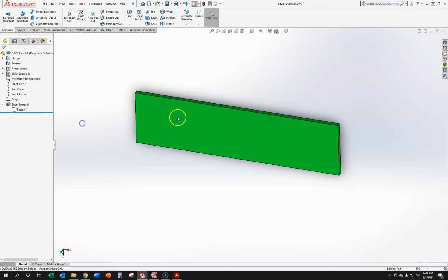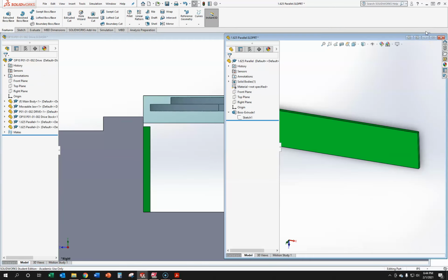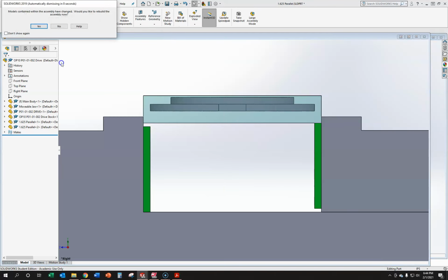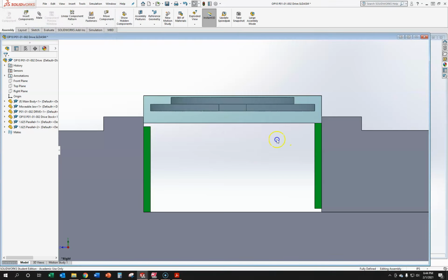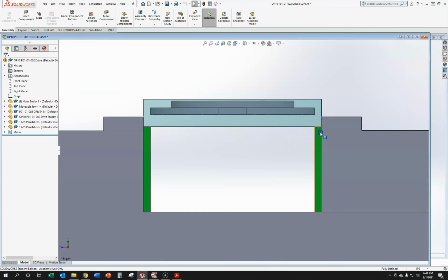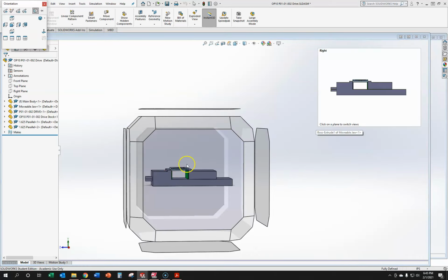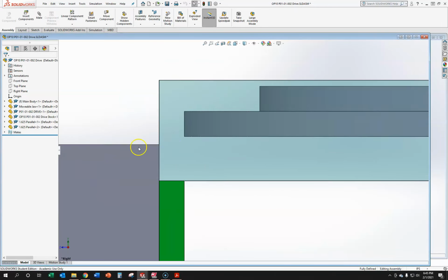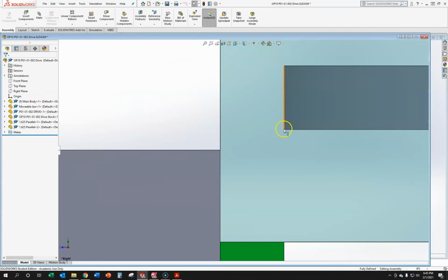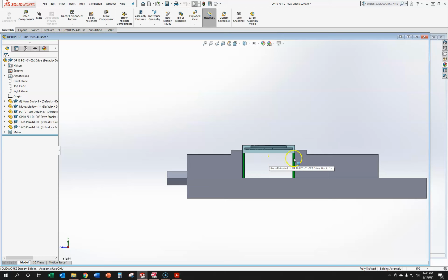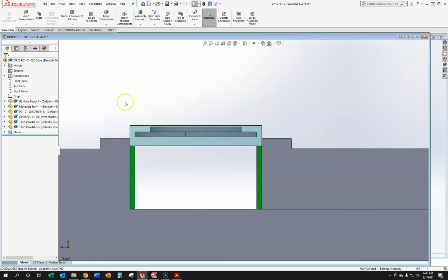We'll exit the sketch. And now really simply, I can click on that button over there to put it on the left-hand side. When I come over here on the right, it's going to ask to update and rebuild the assembly. If we click on yes, you're going to see that it actually lowered the sizes down. It updated the file, and you can see now that we've added an additional almost 1/8 of an inch of work holding here. And we can also confirm that we are still well above the vise jaws. So by changing that to 1.563, I think that's a much better strategy there.